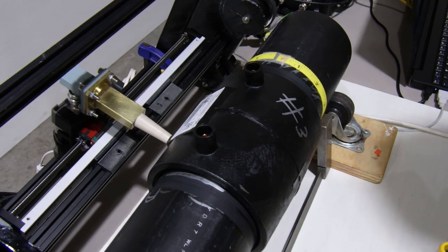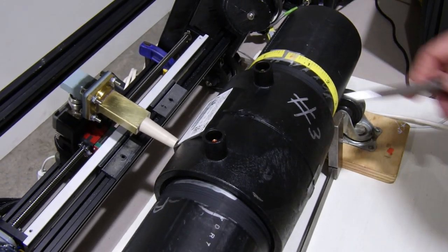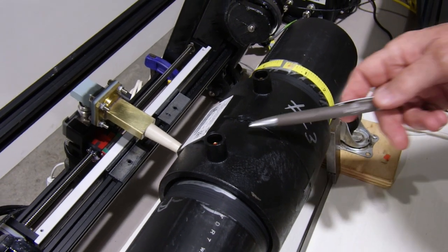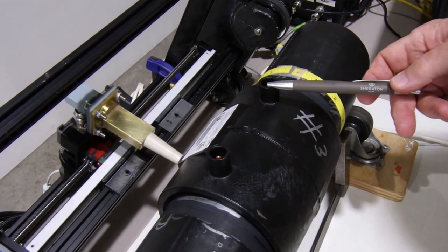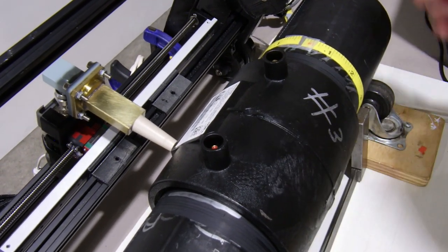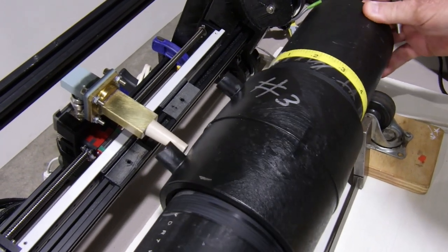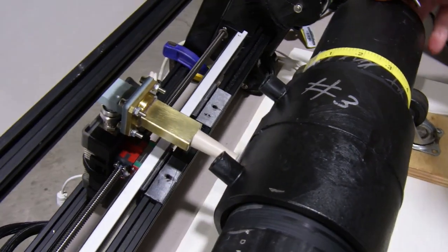Now that we've got the software set up, we've selected a joint to put in the fixture to scan. This happens to be number 3. We do want to point out the posts are still present on the coupler. We will leave those on the coupler, and when we scan, we'll scan before it, basically right here, and we'll scan around this way, and we'll stop just before we get to the coupler the other way as we come around.